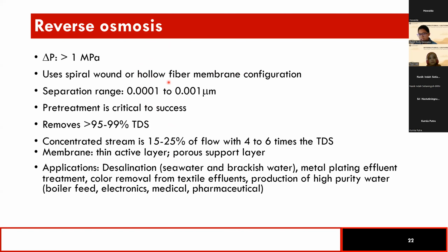Now, I have discussed MF, microfiltration, UF, ultrafiltration, NF, nanofiltration, and RO, reverse osmosis. All of these are pressure-driven membrane processes. So we need to apply pressure to treat the water.